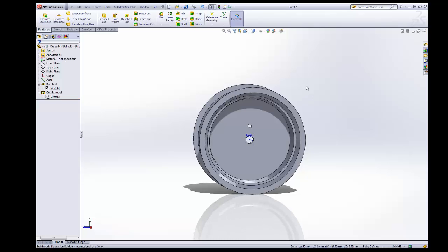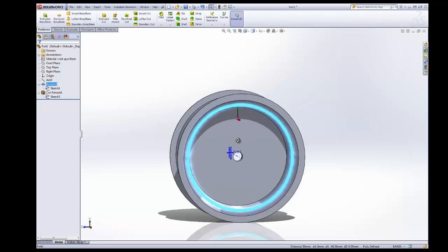Okay, now instead of doing all the calculations and whatnot needed to make it go in 6 places like our drawing had, I'm going to simply use a circular pattern. Well, you don't see circular pattern up here. It's because it's on one of these little flyouts. There's so many different things available to us based on these flyouts that it's worth just trying them out sometimes. But here's our circular pattern,